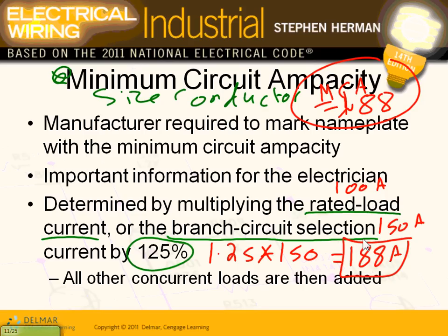That's exactly how they do it. They take the rated load amps multiplied by 1.25, like any other mechanical equipment. And then, obviously, if you have other equipment, relays, whatever, you add the full load amps. Remember, if we have a feeder feeding multiple motors, we add 1.25 times the largest plus all the full load current for all other motors.